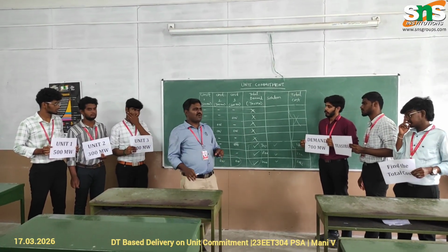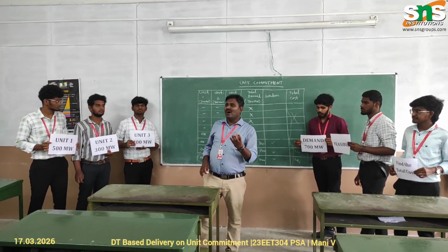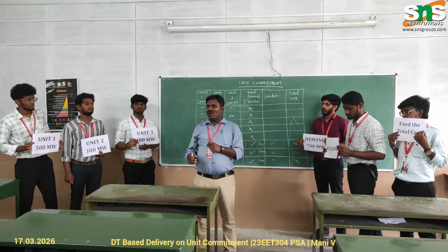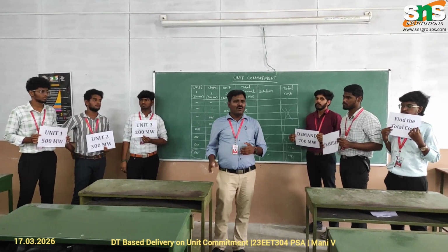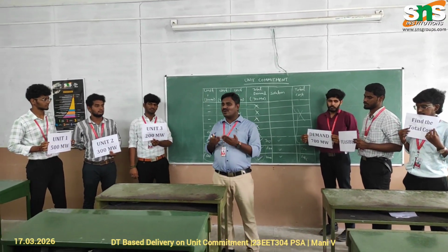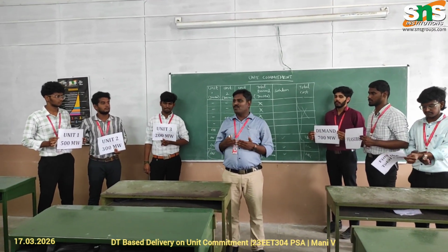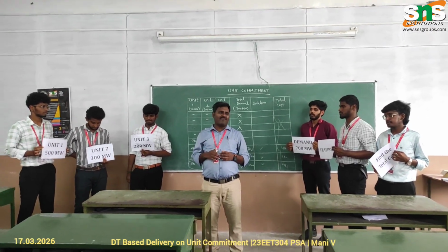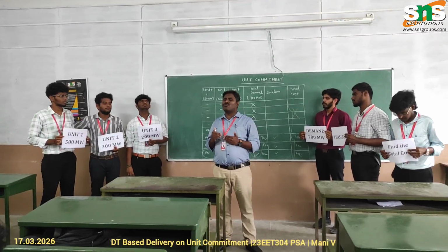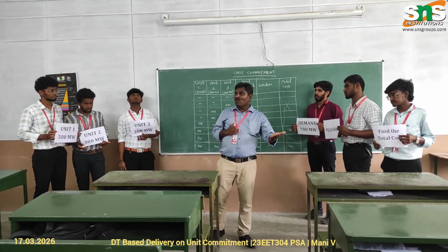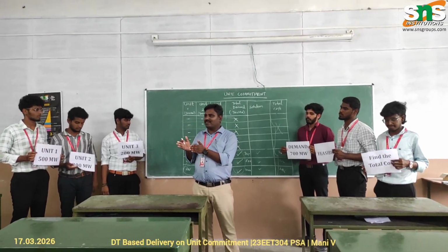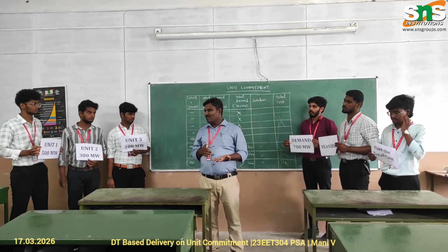Apart from this, we always choose thermal power plants for the base load, because in a thermal power plant, if the load suddenly increases, we have to inject more coal, more hot water and more gases into the boiler. We also have to supply a lot of water to the boiler, and it is getting boiled. It takes nearly 4 to 5 hours to convert into high-pressure steam. But within those 4 to 5 hours, the peak demand goes out.